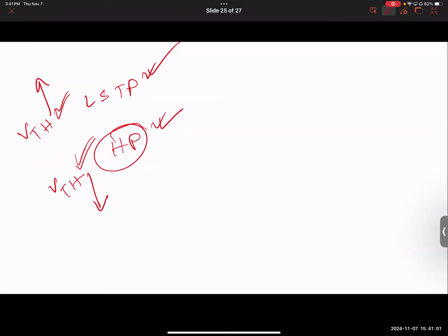Does that make sense? And they do all this by using this seemingly simple phi ms tuning, metal semiconductor work function tuning. That's the easiest thing to do. The hardest thing would be to change the metal, like instead of gold, use copper. It's easy to say, but all of your tools, billion-dollar tools, are set for copper. You're not going to switch over to silver tomorrow, right? Not going to happen.